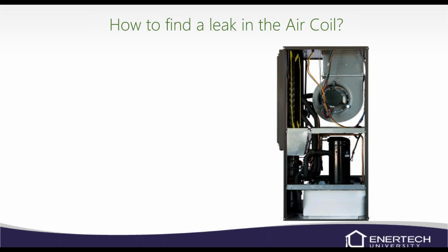And it's going to be a fairly small leak. And I've also found that at 300 psi, I can't hear the leak. I've got just the air coil sitting on a bench in the lab, so it's a lot easier for me to put my ear down there and listen. And at 300 psi, I can't hear it. At 400 psi, it's almost like it breaks it loose, and you can actually hear it leaking. So that's what I would always check first, is those four corners to see if it's leaking, and look for oil in those four corners.